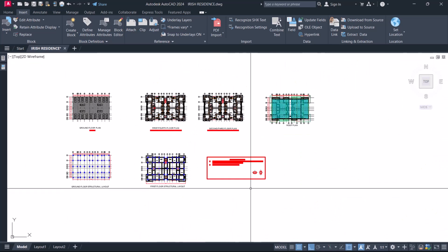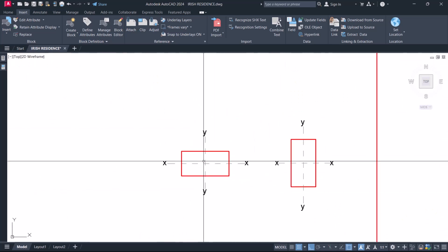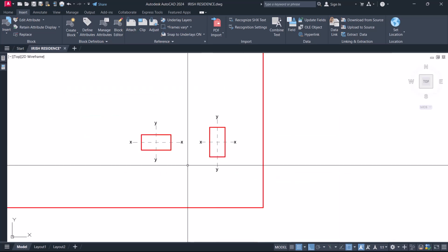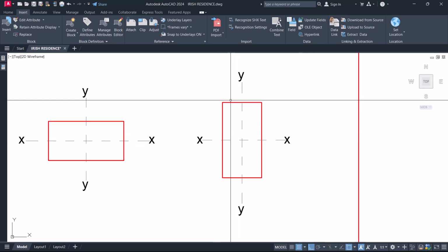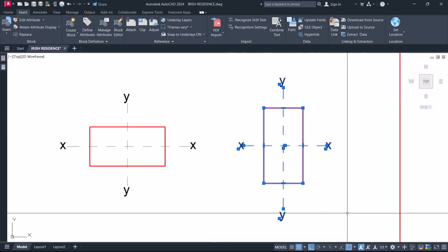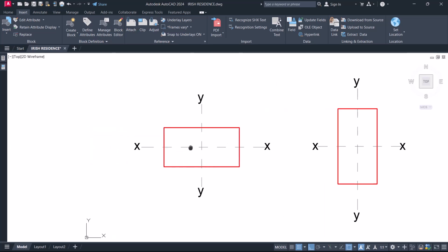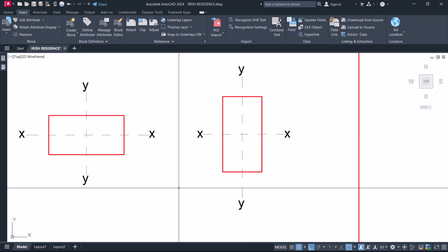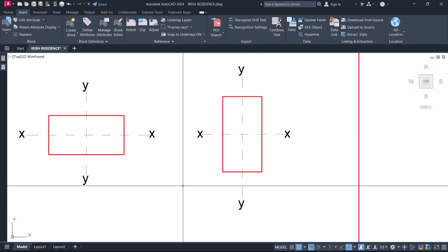This is not a very good practice in structural engineering, because the moment we switch our column from this orientation to this orientation, it immensely changes our major and our minor axis by 90 degrees. So what it does is, when the load is being transferred, the major and the minor axis of these columns will change at that very point.